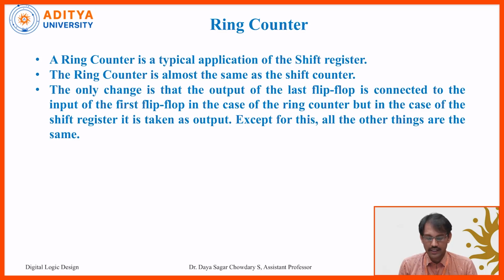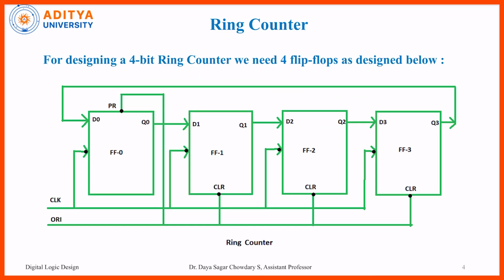The only change is that the output of the last flip-flop is connected to the input of the first flip-flop in the case of the ring counter, but in the case of the shift register it is taken as output. Except for this, all the other things are the same. We will discuss all these things in the next slides.